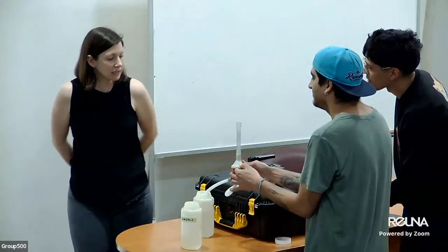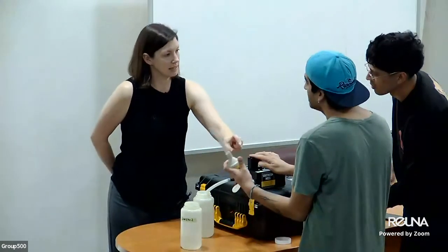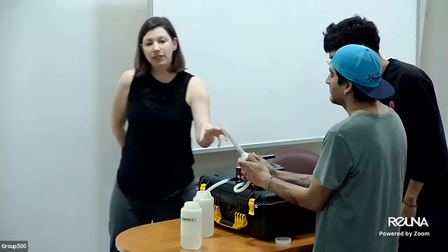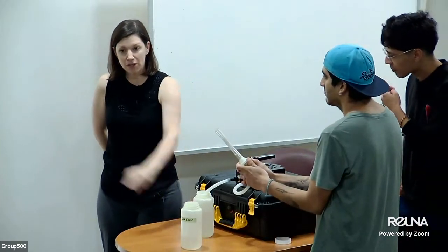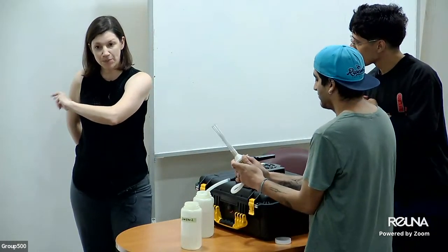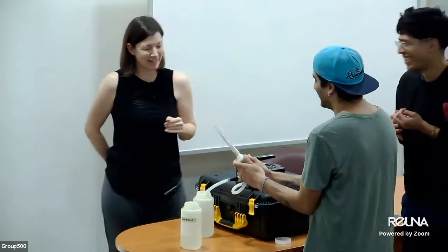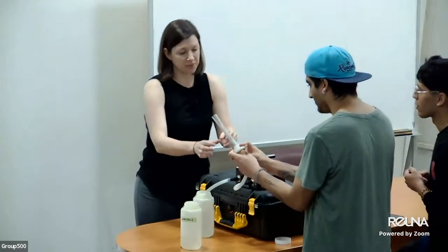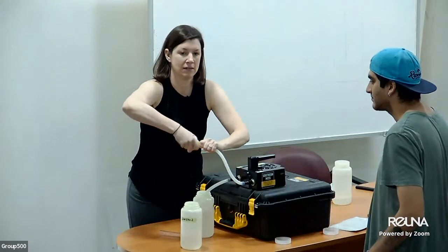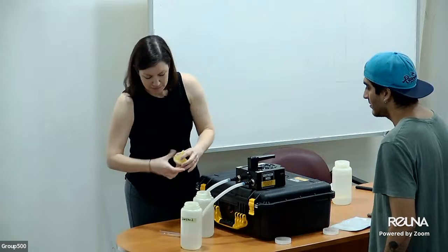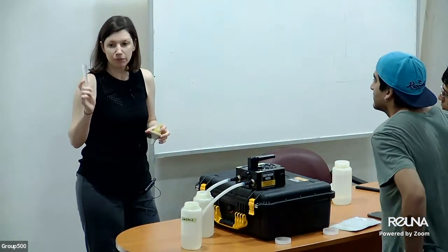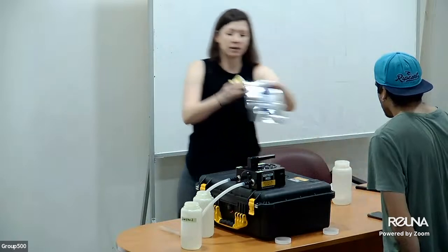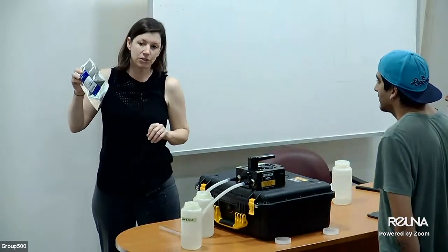Now this water was really clear. You do it for 30 seconds. This filter, I don't expect to have a lot on it because the water was clear. I'm going to show you photos of filters from turbid water. Very different. I showed you yesterday. Okay, that's probably good. So then what you would do is you would take this apart. These you recycle, or you can reuse them if you bleach them and wash them. This would go back in here, seal it up, and then it's good for 6 months.